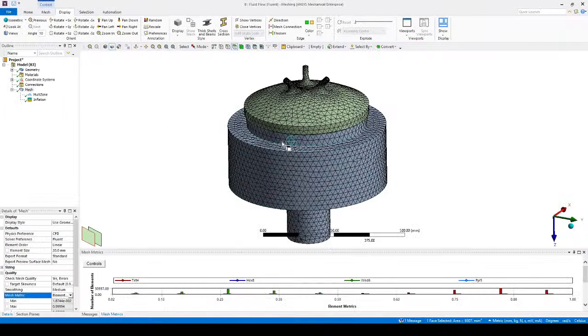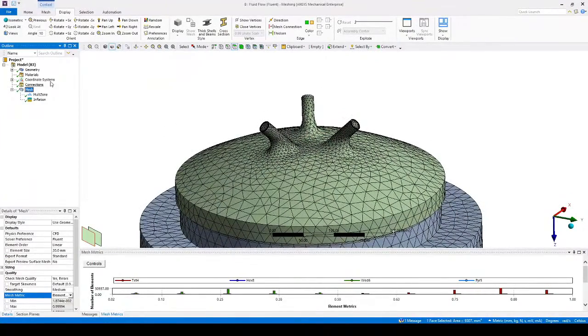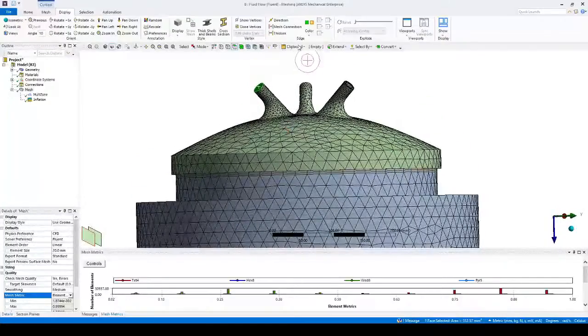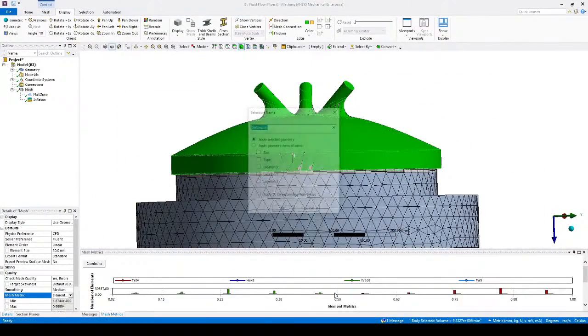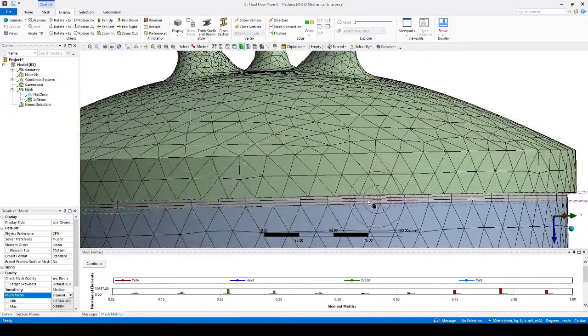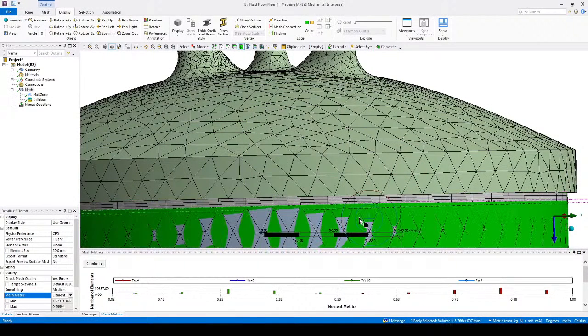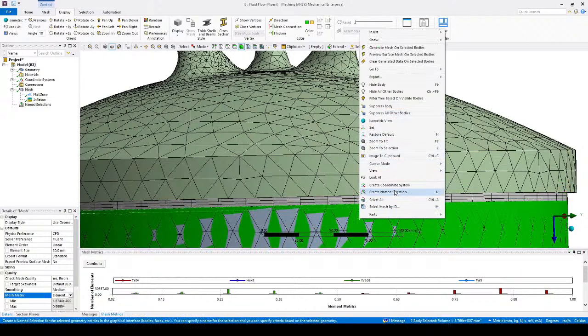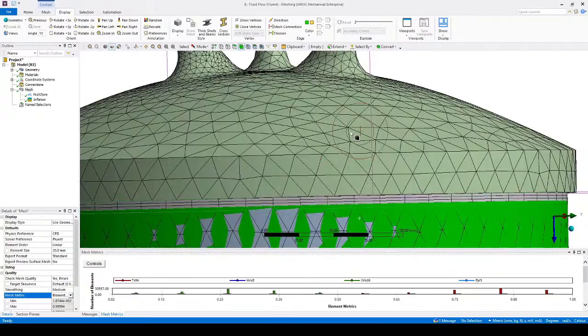The next step we want to do is make sure we assign our boundary conditions. So we need to flag the surfaces as well as the volumes in the analysis. So this will be my top volume. This will be the porous volume. And then on the bottom, just for completeness, volume here.